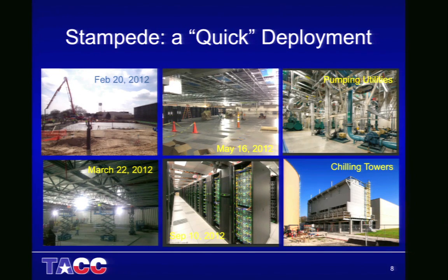Now, this is before it's done. So we have a hot aisle containment system. So when it's done, there's a roof. This is the cold aisle. Right here is the hot aisle. There'd be a roof on top of that, and there's a door on it now. And these in-row heat exchangers basically take cold air from the floor, run the hot air over the heat exchangers, and exhaust ambient back into the atmosphere. And that's what's carrying about 99% of all the heat load.